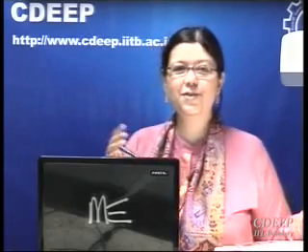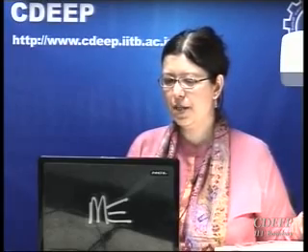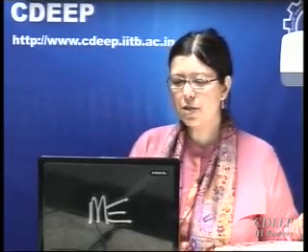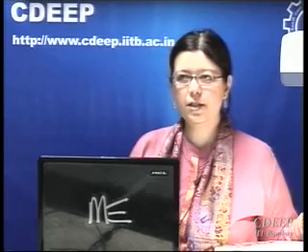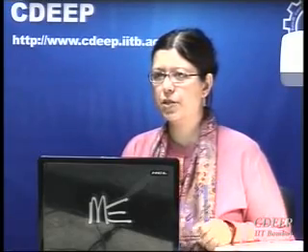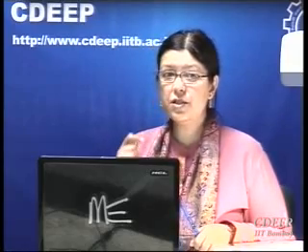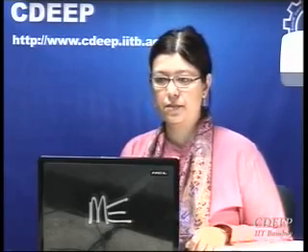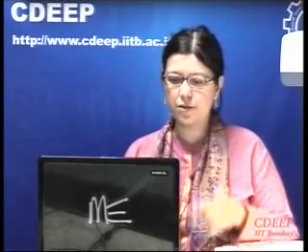And we don't know, because that really determines your gain per stage. So see really how much this amount of 0.05% mismatch will give you non-ideality compared to the case where you don't have any mismatch. So first you can just consider you don't have any mismatch, you derive all plots, and then you apply this 0.05% mismatch. Because now this is a change in the gain of every stage, the ratio of two capacitors.